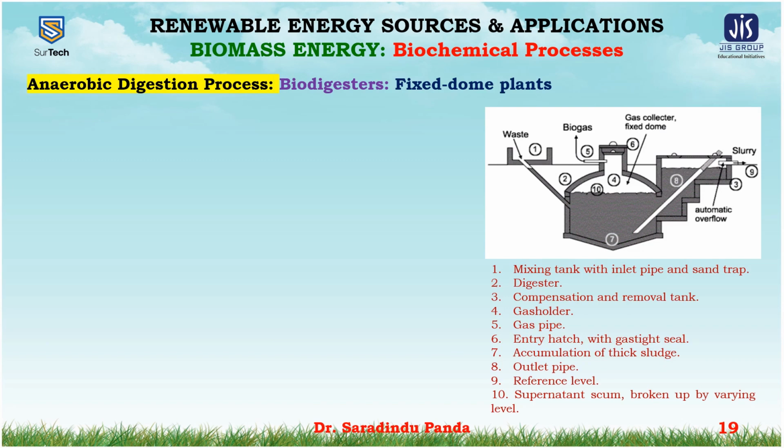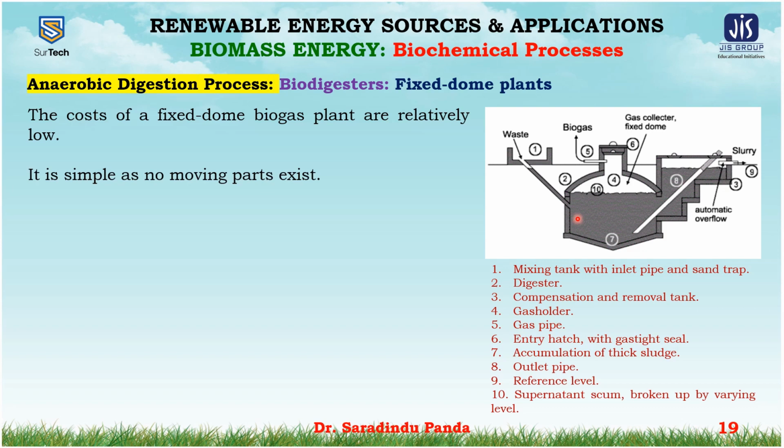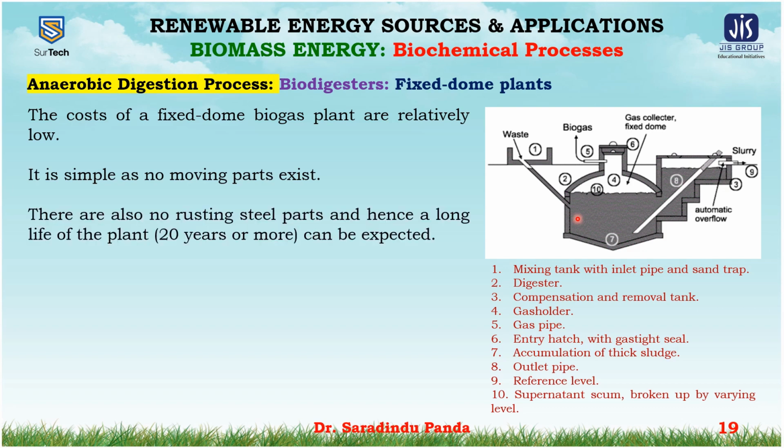Now come to the fixed dome plants. The cost of a fixed dome biogas plant is relatively low. It is simple, so no moving parts exist. There are also no rusting steel parts, and hence a long life of the plants, approximately 20 years or more, can be expected.